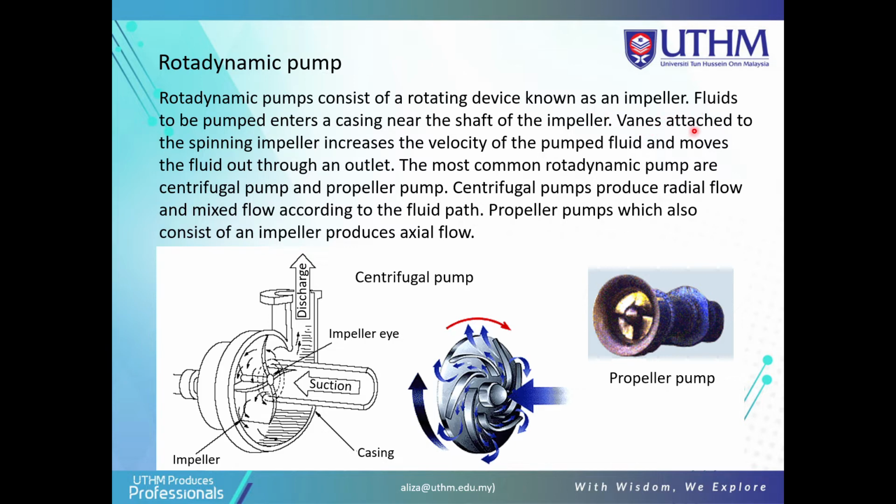Vanes attached to the spinning impeller increase the velocity of the pumped fluid and move the fluid out through an outlet. It is based on this impeller. The suction is here, and the discharge is here. The water is discharged through this flow from the pump. The most common rotor dynamic pumps are centrifugal pumps and also propeller pumps, so remember that.